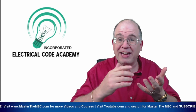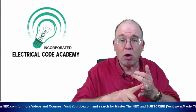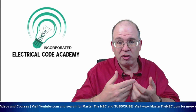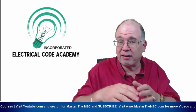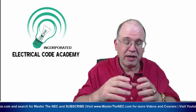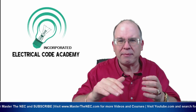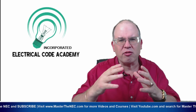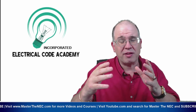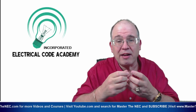So if you've got these situations where you have higher harmonics, you have to have a K-factor transformer. You might have to oversize the neutral because that neutral is going to have a lot of current flowing on it. Well, obviously, you're going to count that conductor as current carrying because of that. Now, that example, the bucket, is an oversimplified version of it, but that's what happens. You don't have a perfect waveform. It gets all distorted, all fragmented. And it's hard to have cancellations of loads on a neutral when that neutral is carrying an imbalance, because it's carrying so many values that aren't canceling out, and that neutral could end up being overloaded.